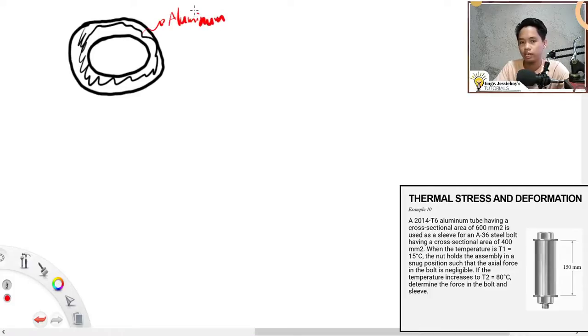Since we are dealing here with thermal stress, we need the value of your alpha. Pause the video and look for the alpha of aluminum 2014 T6. Again, that is equal to 23 times 10 to the negative 6 per degree Celsius.